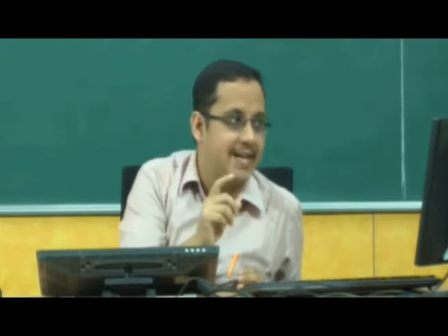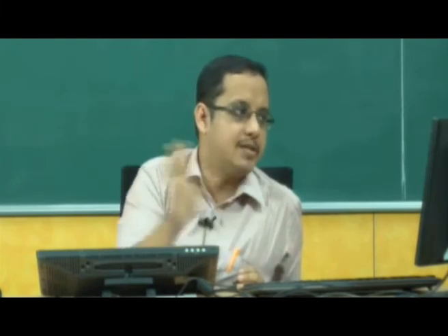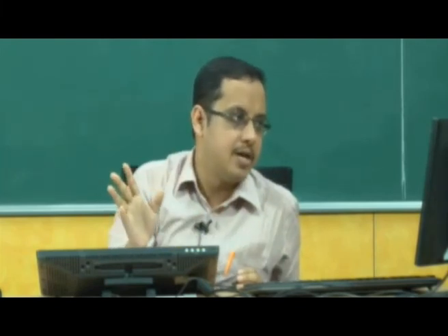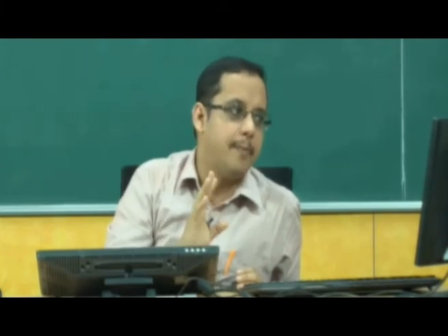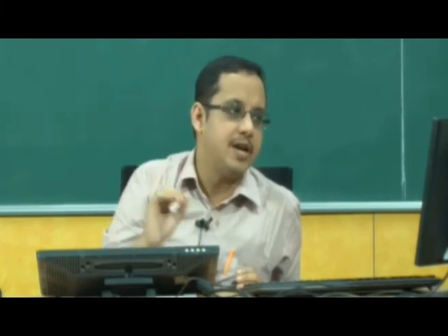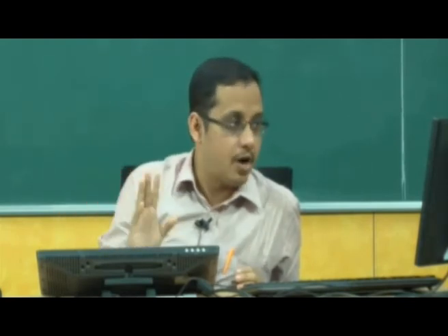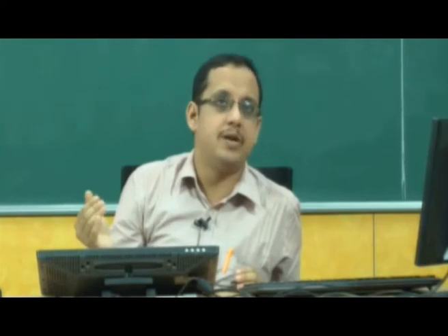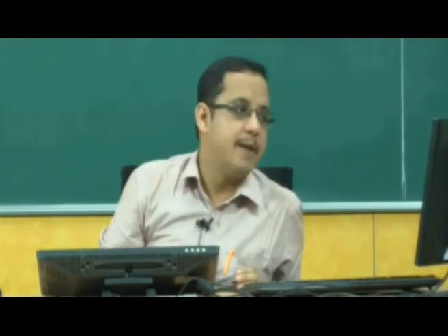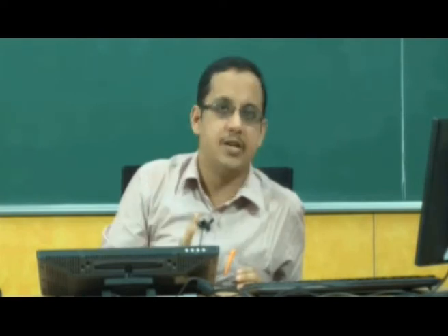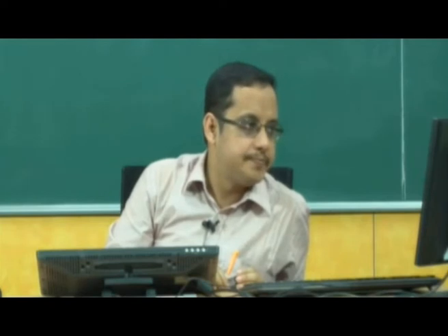slide was about detecting. Firstly, you have to understand whether yes or no, whether there is an unbalance or there is no unbalance. So when I said it is detecting the unbalance, it is only about knowing whether m times e is equal to 0 or is not equal to 0. If it is not equal to 0, there are separate experimental procedures by which you have to actually determine how this m times e has to be estimated in your problem, but that was not talked about in this lecture.